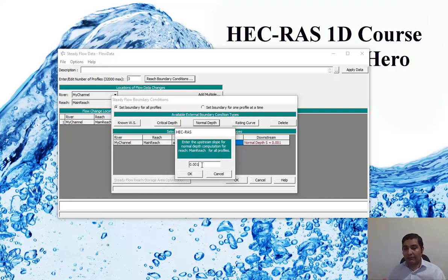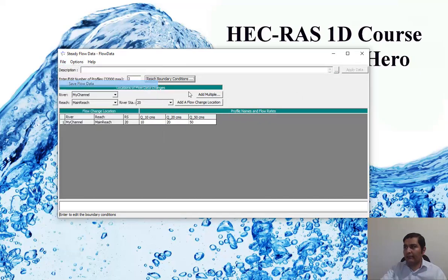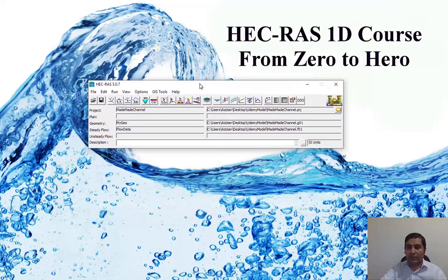If you don't know which of them may occur in your case study, you should enter both boundary conditions. Okay, I will save and close the window and go back to the main window of HEC-RAS.